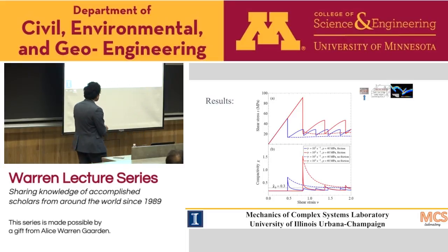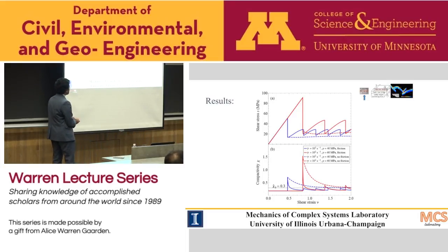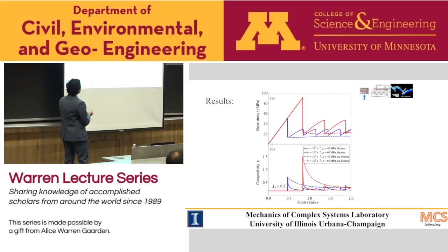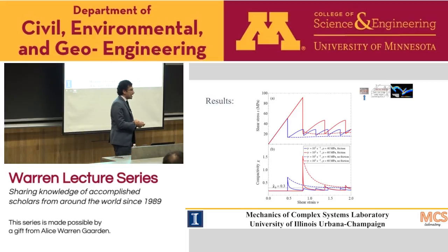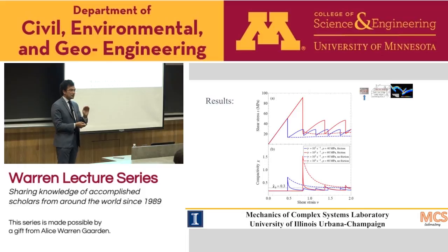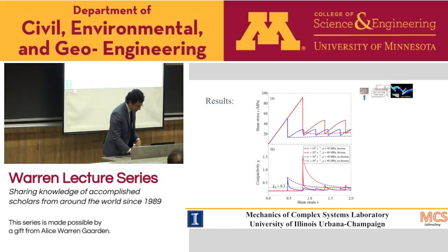So we did validate this hypothesis by testing cases where we have this non-monotonic behavior for the volume as a function of strain rate. So this is at different strain rates and pressure. This curve shows the shear stress as a function of shear strain. And you can see here, if we don't have this non-monotonic behavior, say we have frictionless grains, then you get steady sliding. So you shear the system up to a certain point, then you get strain softening, and then you get steady sliding. Whereas if you have a non-monotonic rheology due to the compaction and dilation, then you get this kind of stick slip. I will talk about this later.